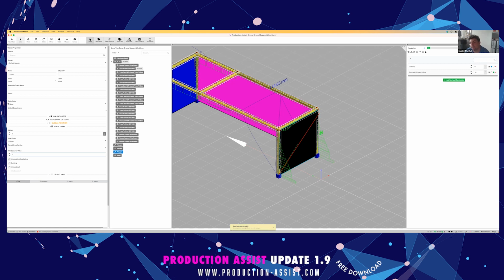That comes from outposts of an advertisement that freely stand in the wind zone, and normally you go down to 0.5. That defines how much load from the wind actually gets applied to the plane. The second option, and the one that's important to enable to get it working, is use as wind load plane. If you activate or deactivate this, the wind load will or will not be used as a wind load plane for the internal calculation.